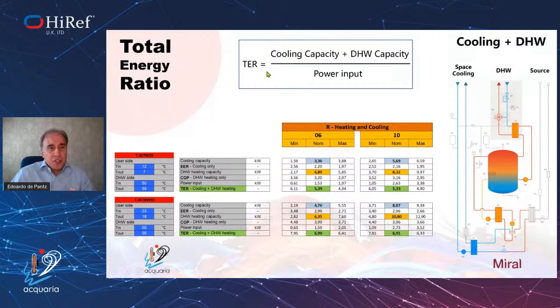This is not a COP. This formula doesn't exist in any standard, in any certification. It's just a way to explain an operative efficiency of the system. In this case, the overall efficiency is very high, but also we are not reversing any energy into the loop. So it's a double benefit, if you want, in this special operating mode.